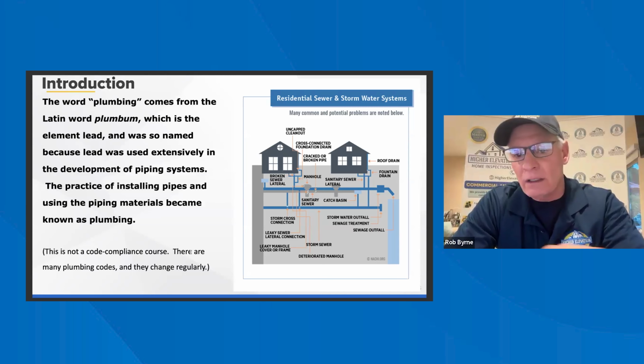A lot of times, when you're at the fixtures, especially at a sink, they have that screen on the bottom of the faucet. A lot of times we'll open the aerator, open up the supply, and there's a low flow, but the flow was great throughout the house. If you unscrew that filter and clean it out, it'll change the pressure, because all of the sediment that's in the pipe is going to be affected by that.